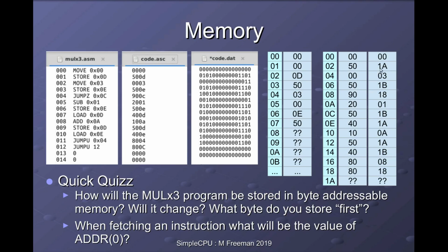And that's because we've gone from a 16-bit memory to an 8-bit memory. In the original program, if you go back here, we're storing the data value out to address D, address 13, because that's the next free location. But as each instruction now takes two memory locations, the address that I want to write to is effectively doubled. So rather than 13, it goes to 26. And obviously, if you know your hexadecimal, I've got 1 16 and a 10, so 26 there.